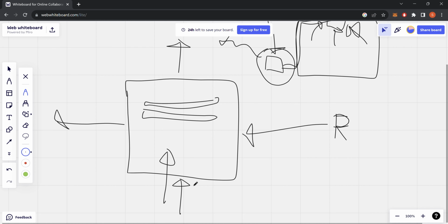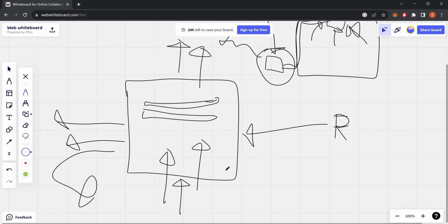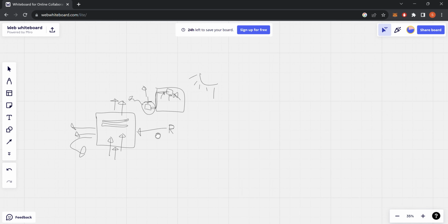And what that's going to do is pull that heat. Those aluminum fins are going to heat up because that excess energy from the house was pulled through with the refrigerant. So the air is going to go through here and pull that heat out of those coils. And then the refrigerant that's leaving this is now going to be cooler. It lost some of that heat because the air sucked it out. And then it's going to go back towards going back into the house, right, to pick up more heat from the house. So that's the basic condenser.